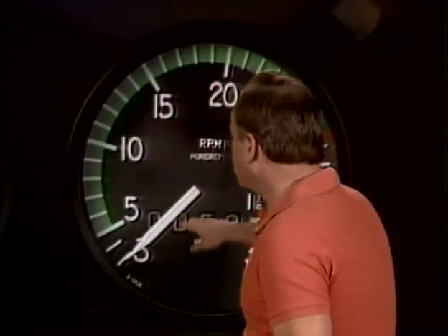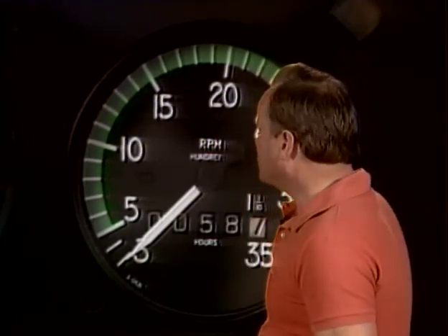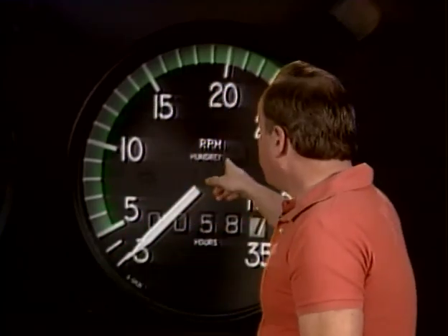Now, let's talk about tachometers. The FAA wants you to know a tachometer, of course, which measures RPM, is a primary engine instrument, meaning you have to have it. How do electric tachometers work? Well, they're using what are called synchronous motors. What you have is on the engine, you have an AC generator that puts out an AC frequency, and the indicator will have an AC motor, and those are called synchronous motors. The way it works is that as the generator turns, the motor that is associated with the gauge turns in exact synchronization with it, so they both turn together.